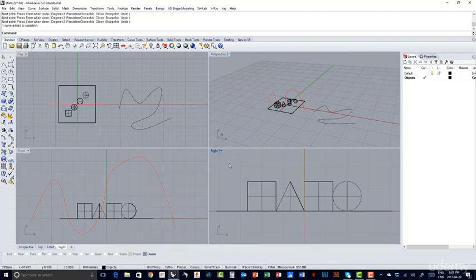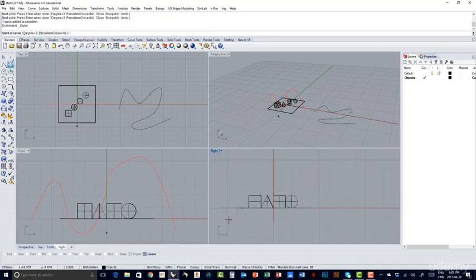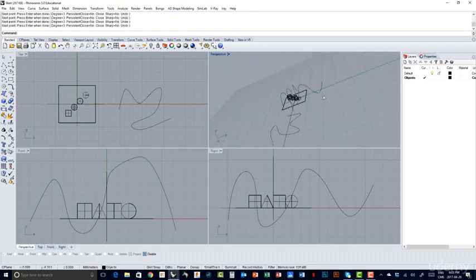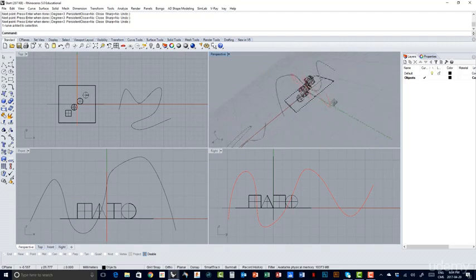And if I go in the right viewport, it's the ZY plane that I'm going to be working on this time. The ZY plane in perspective, you see, goes like this. So I use my curve tool, and I can start sketching on that plane. The grids that you see in the right and front viewports are independent from the grid that you see in perspective. You just need to remember that. Whatever I sketch in the right viewport, you can see it here, and you've got a nice 2D curve. Okay, so just remember that.